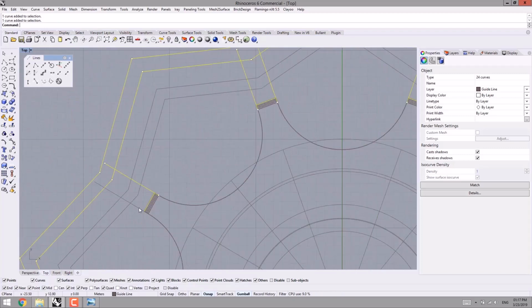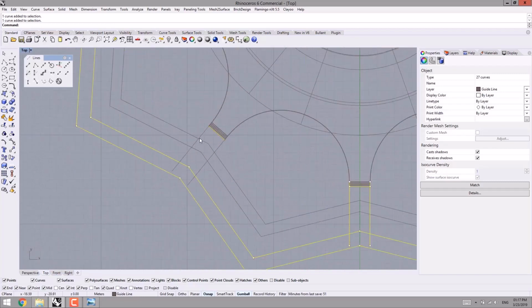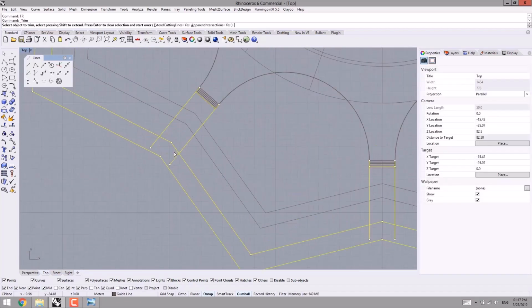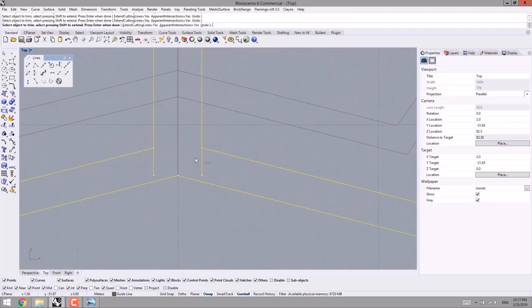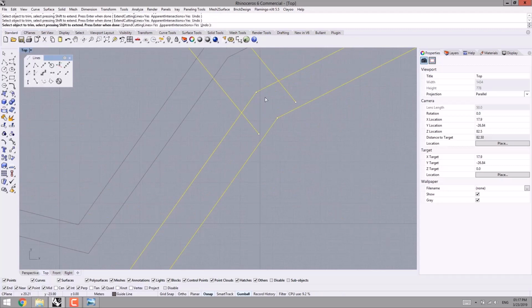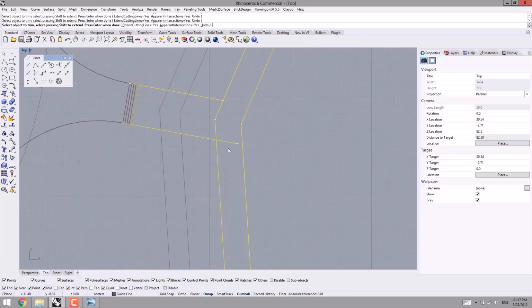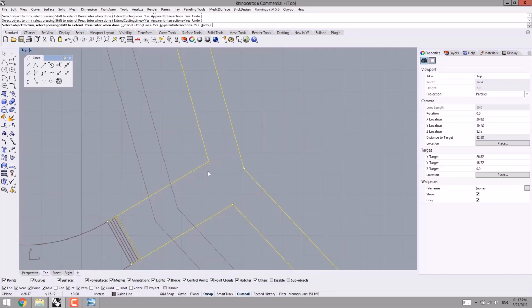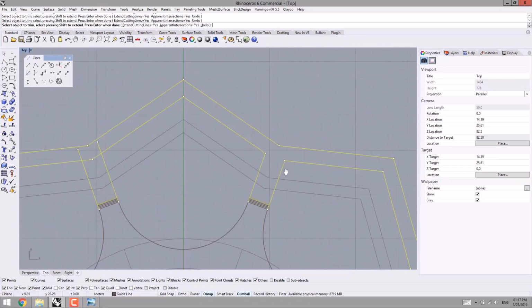After that, I'm gonna start the command of curve boolean to create a closed curve. Wait for a second. Before that, I wanna trim some parts like these. I trim the extra parts. However, we can keep them untrimmed, and then in the command of curve boolean we can combine them.